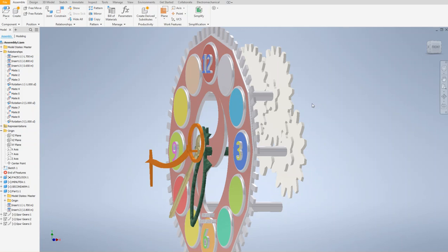ratio, proportions of the number of the teeth between 2 gears. And so 60 was too big, yielding one very, very small gear and one very huge gear, so we didn't want to go with that. We wanted to divide the 60 into smaller parts. So 60 can be the product of 3, 4, 5. 3 times 4 times 5 gives you 60.